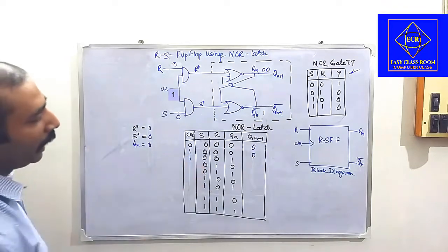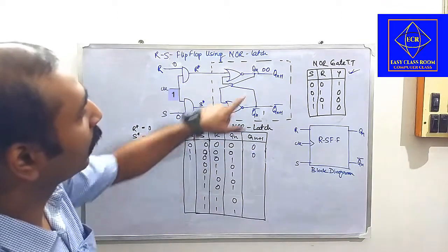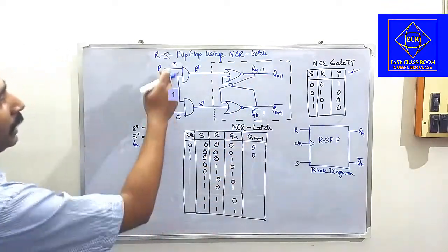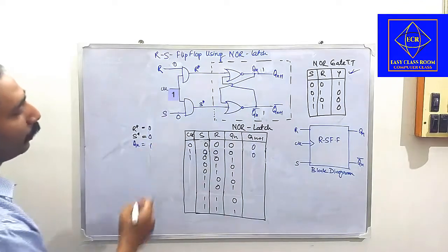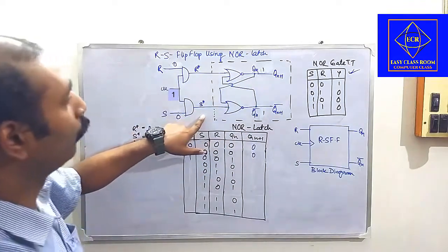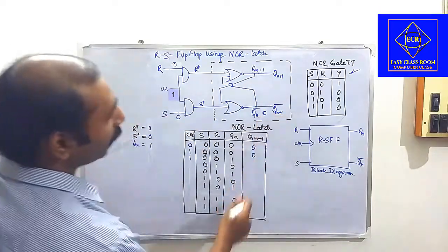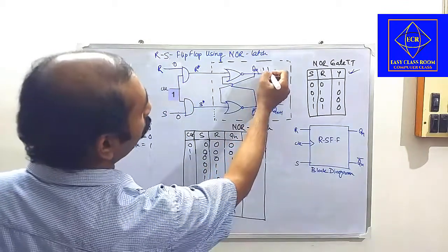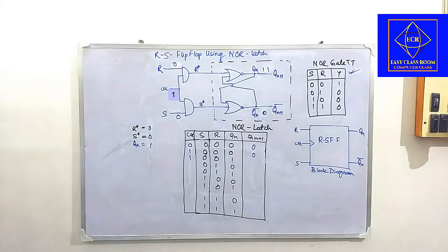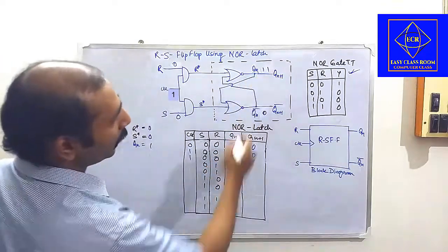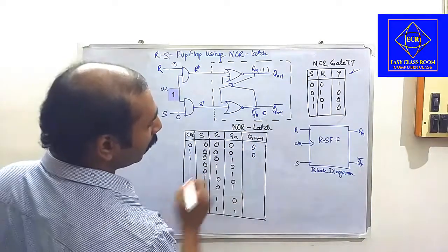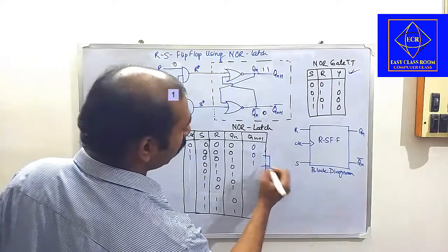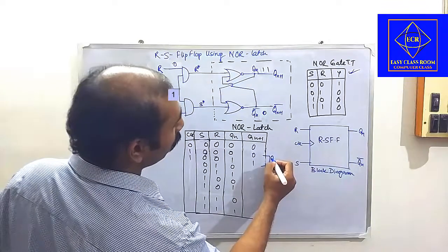Now, if we give the same thing with QN is 1, QN is now high, what happens? So if the QN is 1, these two are 0. Here QN is only 1. This 1 and 0, we will get a 0 over here and this 0 will come up here. So 0 and 0, we will get a 1. Okay. So we see now if we have given 1 over here, we are getting 1. So if we are giving 0 here, we are getting 0. So what we are giving is what we are getting. So we can say clearly this is a memory state or QN state.